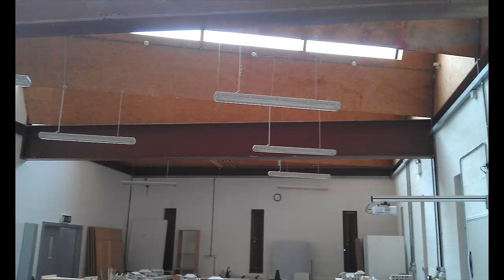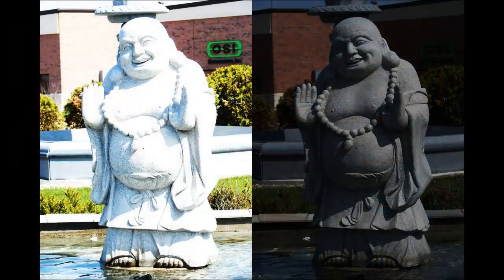Light is a significant factor that needs to be considered when trying to capture an object using 123D Catch. It has been found that natural light produces much better results as fewer shadows occur on the surfaces of the object. Therefore, a room with as many windows as possible is advised. An object can also be photographed outdoors. This, however, may not always be suitable.